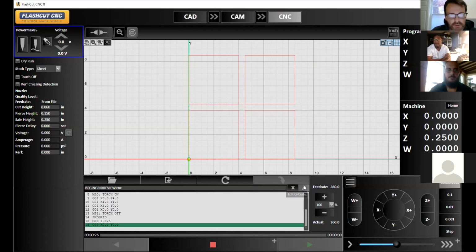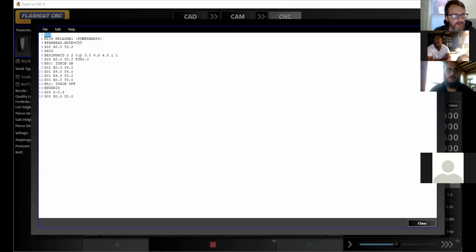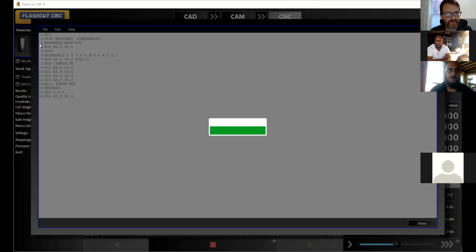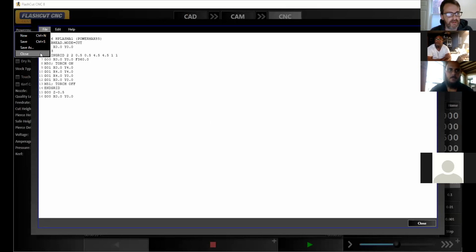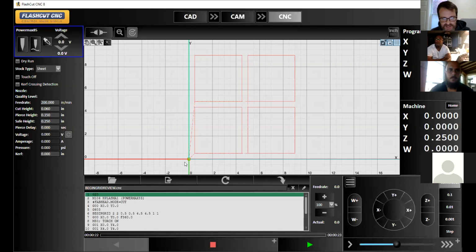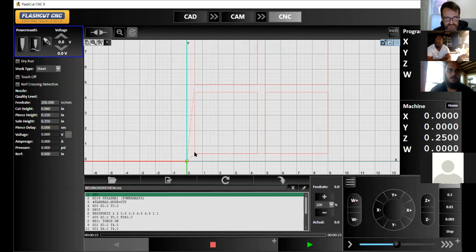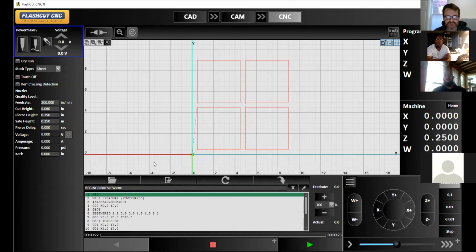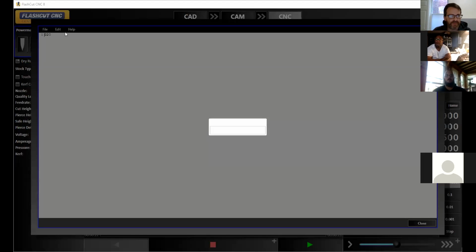Oh, okay. So say we go back in here, we want it to start at X 0.5, Y 0.5. We still keep the spacing because that stays consistent between each part. So now instead of starting on the axis, we're starting at a 1/2 inch in the Y direction and a 1/2 inch in the X direction. And we can make this any number that we want.